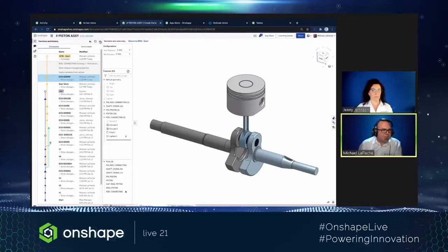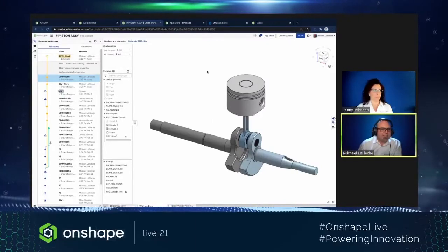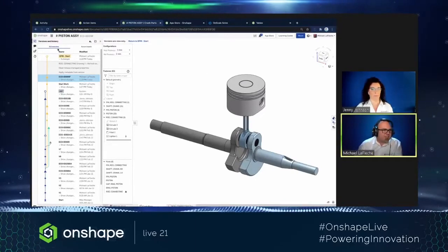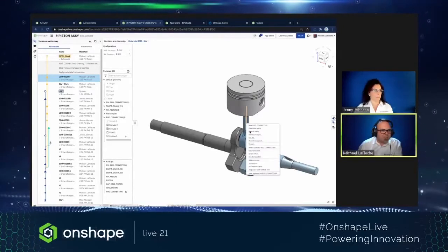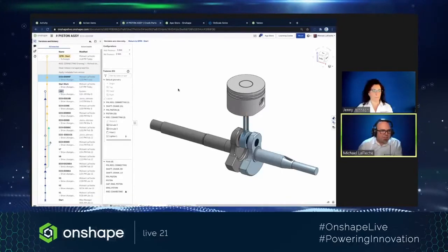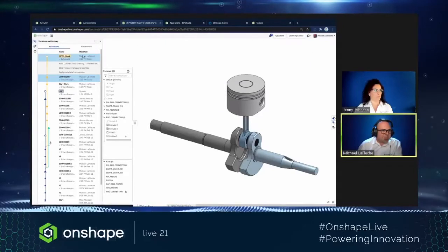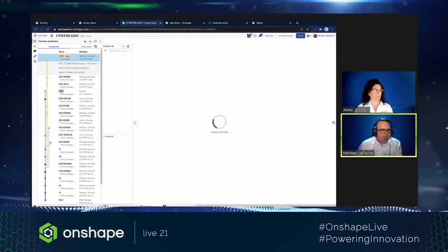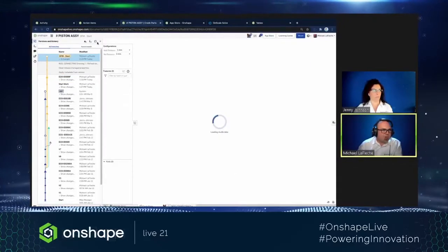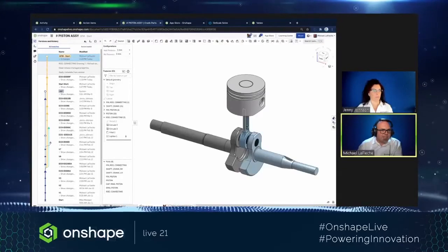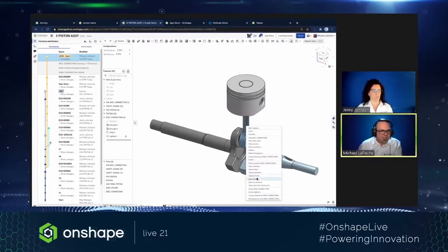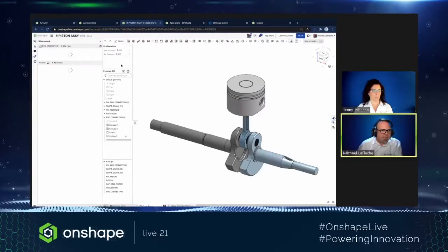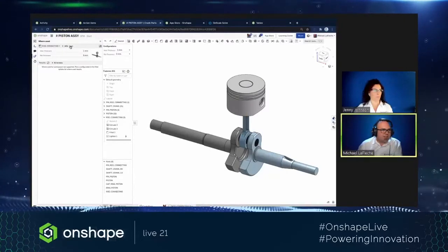And the final thing I want to do is note to Jenny that there's other places where this connecting rod is being used that we need to check what's going on. So we should do a where used report on this particular design. Let me actually do it from the workspace. That way I get the most wide range of reports available here. So I'll right click here. We'll do the where used, and it will show us all the places we're using this.